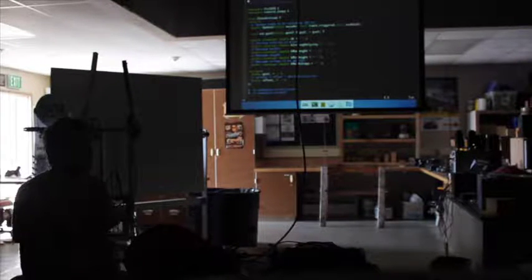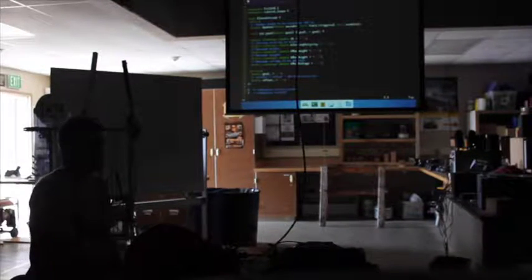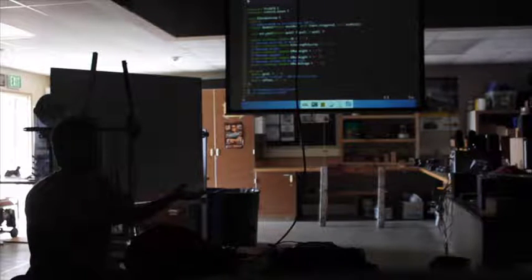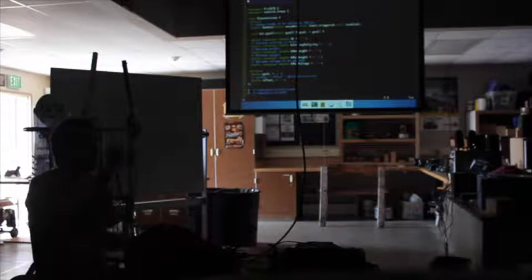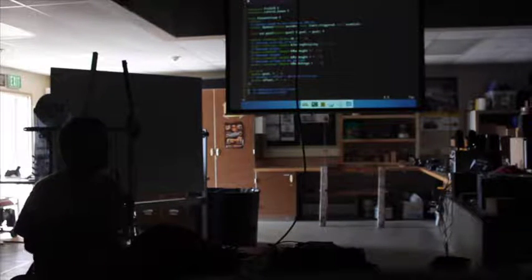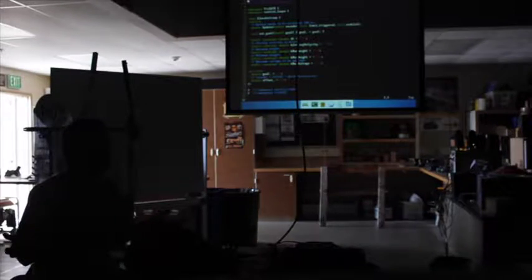So we're going to talk about what's called test-driven development. The idea here is basically that you start by writing a test case. So you have a behavior you want your robot to achieve. Say you want it to move an arm to a position and then stop. The goal is to write some software to verify that our robot does that. And then after you have a test that makes sure it's going to work, we're going to go implement the code to implement that behavior. Does that make sense to people, the basic idea?